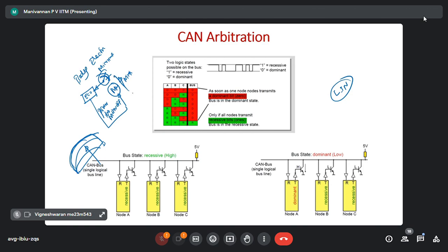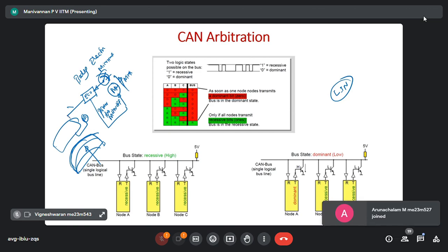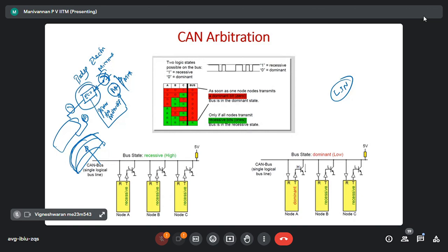This is for controlling one window. Like that, I will control the same thing for the next window: there's a motor to control it and a micro switch, like the four windows. For controlling this, you don't need a CAN bus, because this is one ECU. Now, if this ECU wants to talk with, for example, the ABS ECU, then you may use the CAN bus.